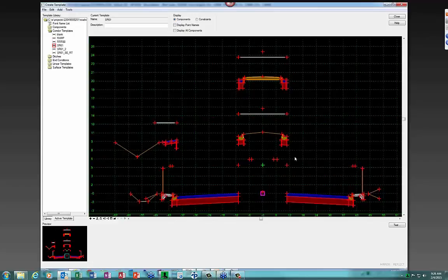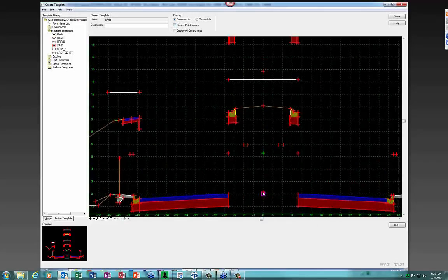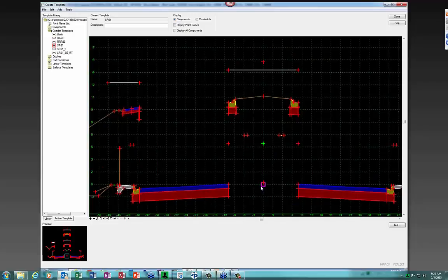In this case, I know what I want to do is rotate my roadways about a center pivot point. So prior to assigning the superelevation to this corridor, I need to make sure that I have a pivot point in here, and then I need to set my edge of pavement lines here, what we call profile grade lines, to be sloped off of the pivot line. That way, all of these will essentially rotate through this point in a superelevated condition.